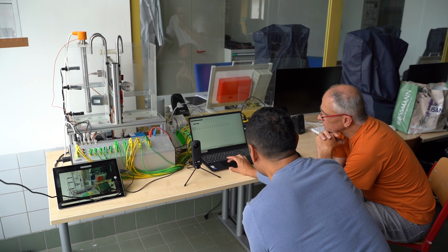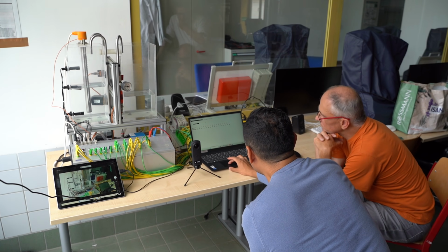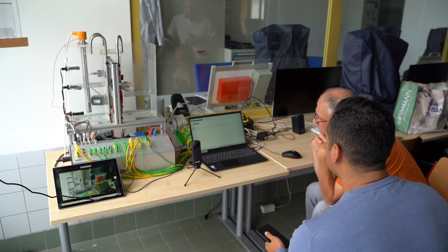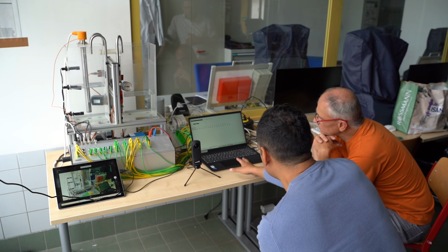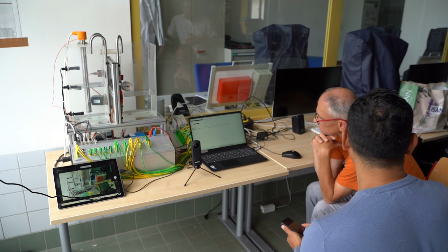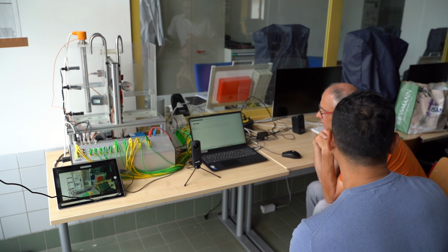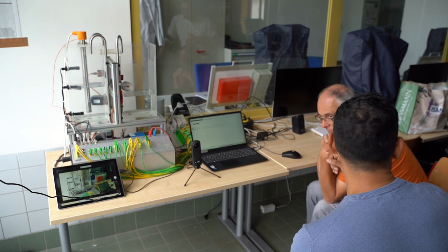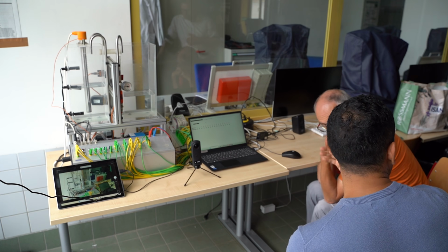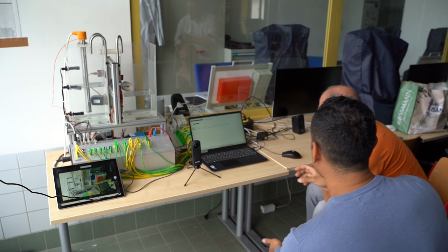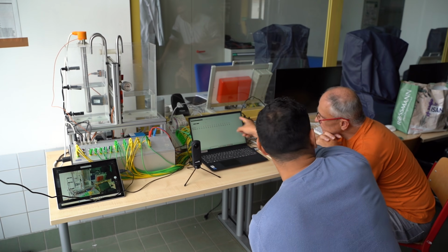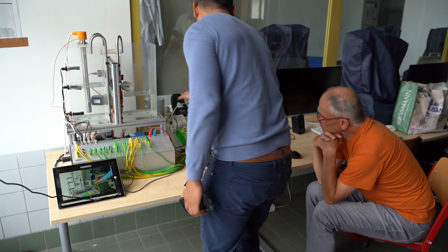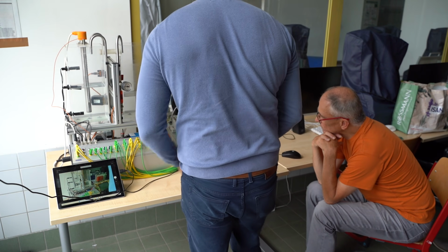So normally the program has this LED. When it's green, it's because it's sending data to our cloud. So basically the whole purpose of this is we have several industrial protocols. As you might have seen here, some of the machines you have there, they are connected through a serial port, which is normally a Modbus connection. This one is connecting through Ethernet, Modbus. This is the technology that is connecting this card to here. So this is the Ethernet.